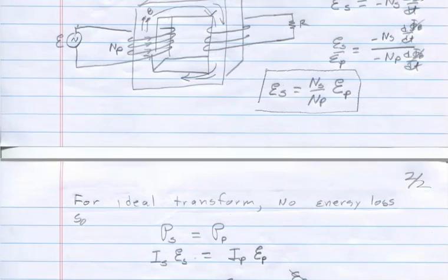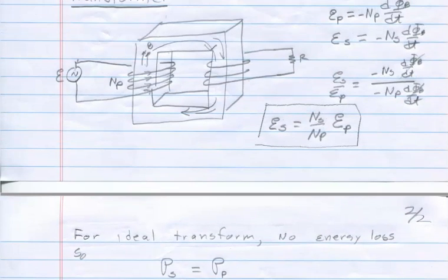What that means is that if I step down the voltage, what happens? Well, if this was 100 and this was 10 wraps over here, I would have 10 over 100, and so I would reduce the input voltage in this transformer to something less. If this were 120 volts, I would have 1/10 of 120, and over here the highest we'd ever get would be 12 volts.